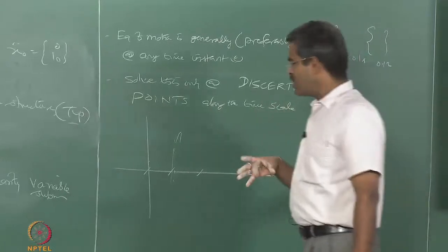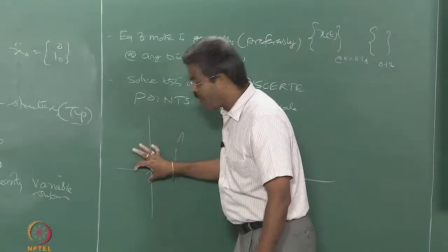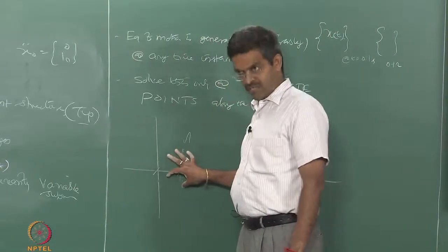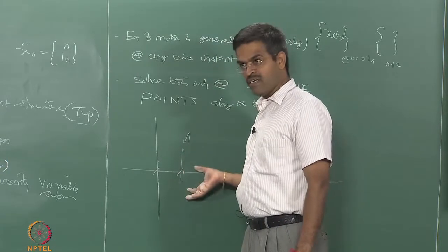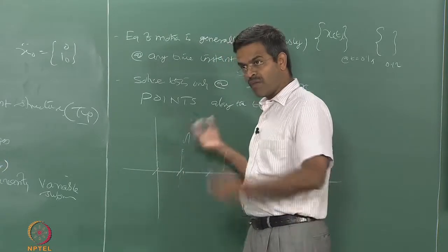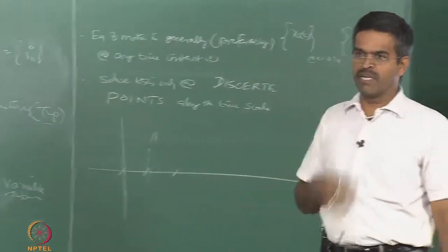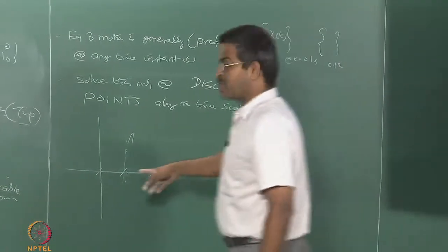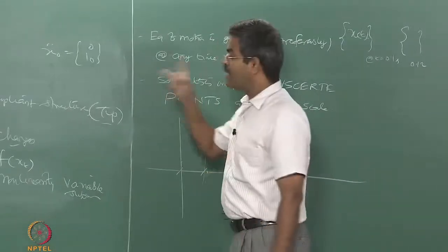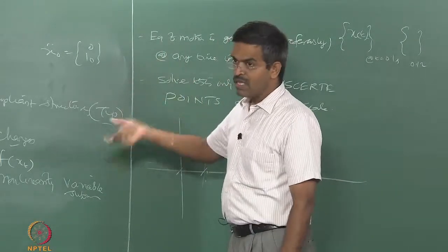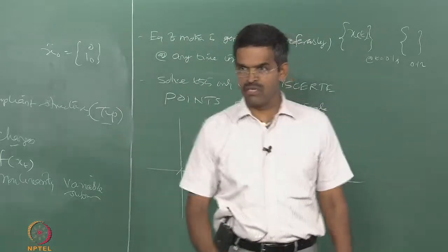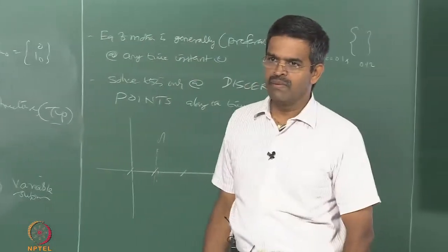So I assume that the previous point values are the same as the values here, and find out the answer, see whether this answer is what I assumed in the beginning and get the same back again. If you do not get it, keep on iterating, in the sense that not only the displacement, you have to start iterating from K, M, C, F of t. The whole equation of motion is getting completely iterated.